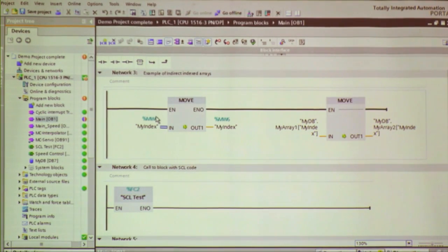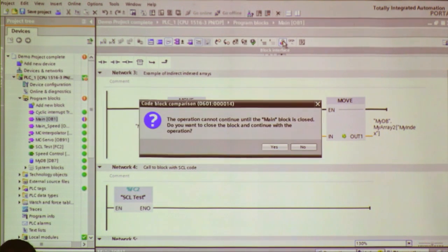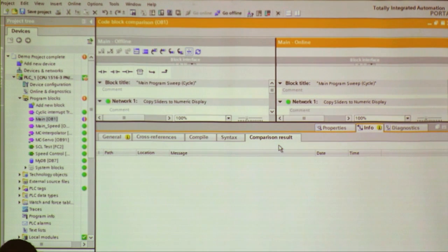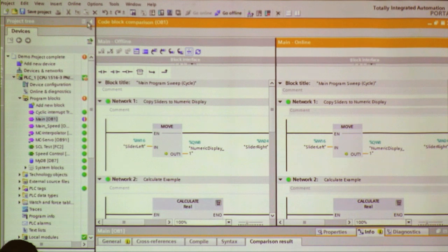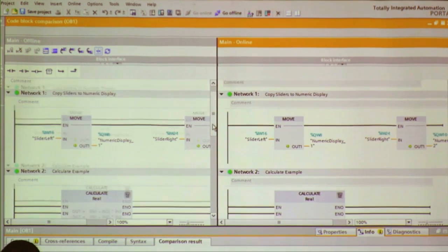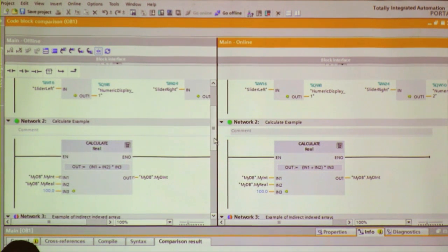But if this block, you can start a big cross-reference or a compare editor, because you see the differences in this block. You can open up this block, and right here in the editor toolbar, you can start a detailed comparison. That's going to ask me to close that down. That's OK. Then I can optimize the space and close this. So I can see a side-by-side comparison, and we can go down through the code and see where the difference is.